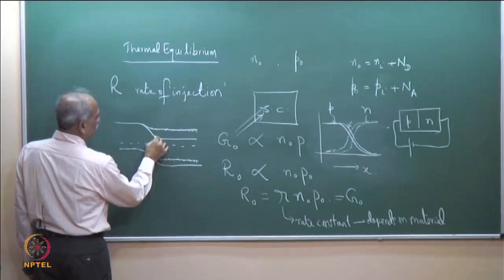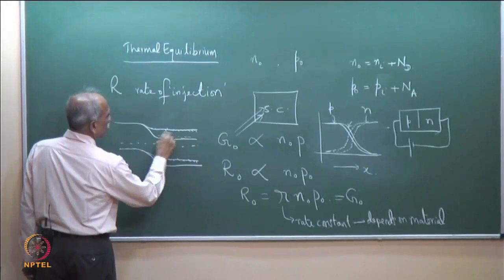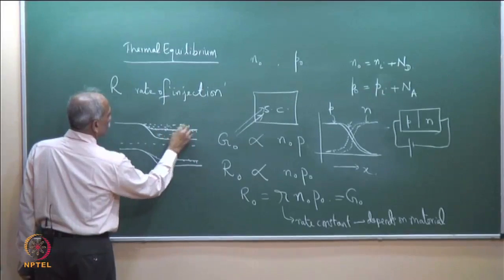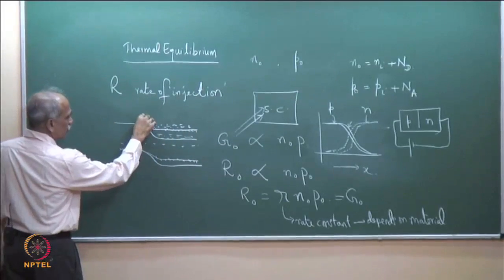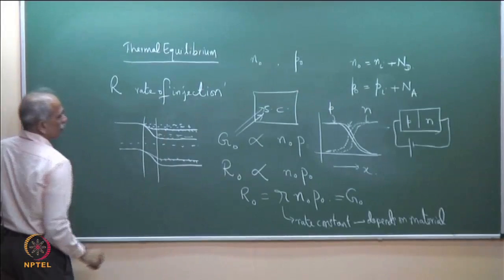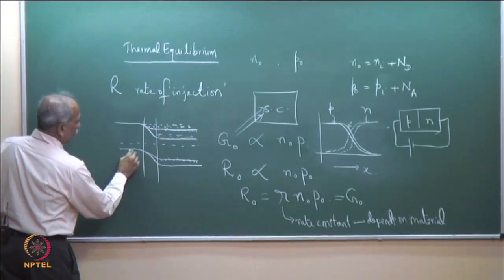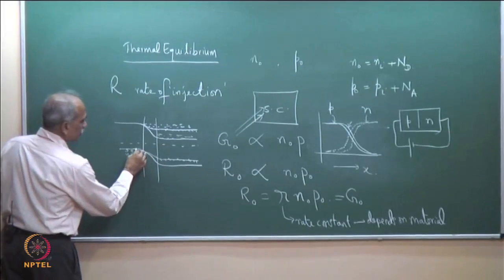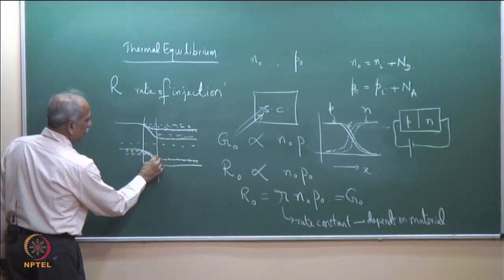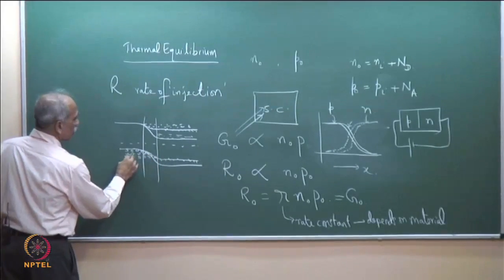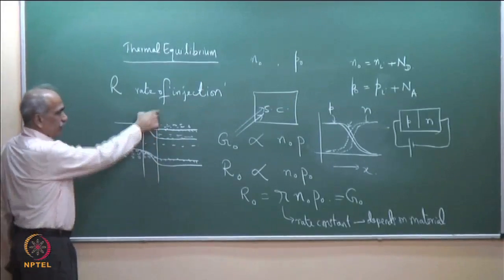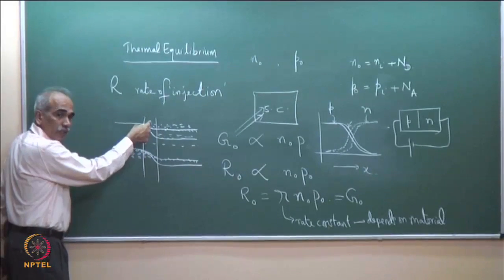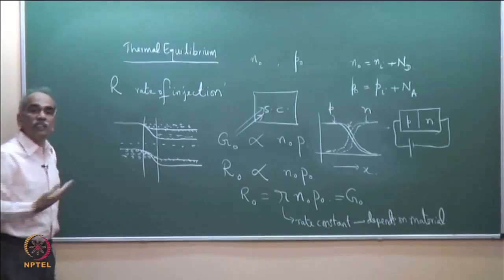Earlier electrons were up to this, now electrons have come up to this, they have moved to this side, and earlier originally holes were up to this. Now, because this band has moved forward, holes have come up to this, which means the junction region here is where we have excess carrier concentration, excess of electrons and holes, excess because of the injection.